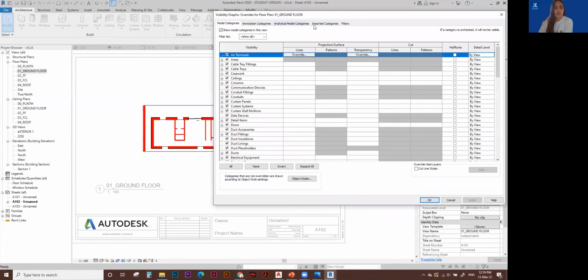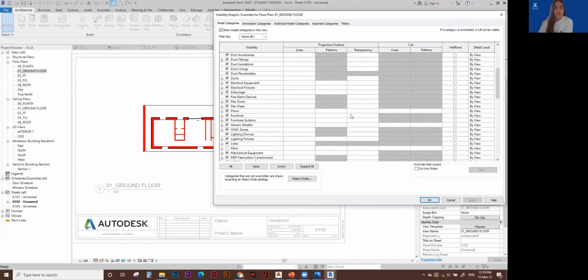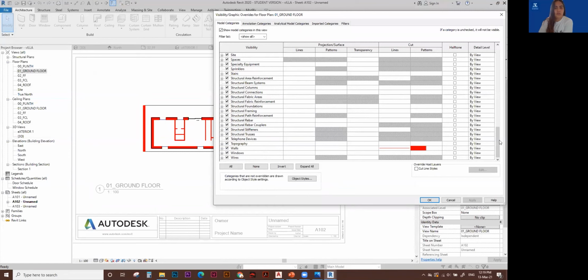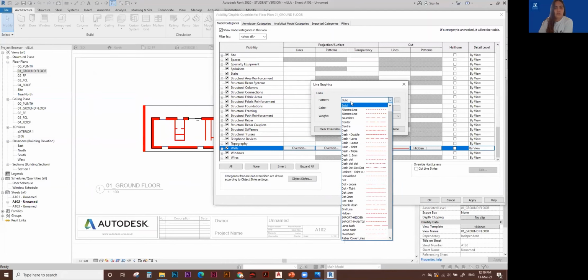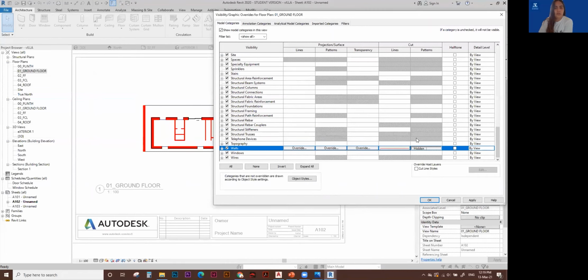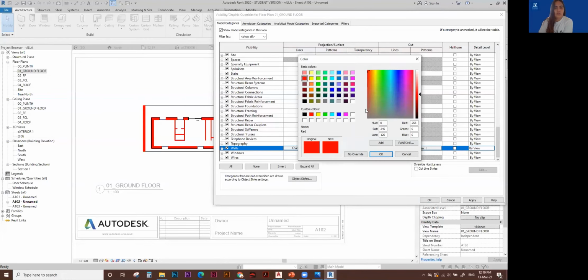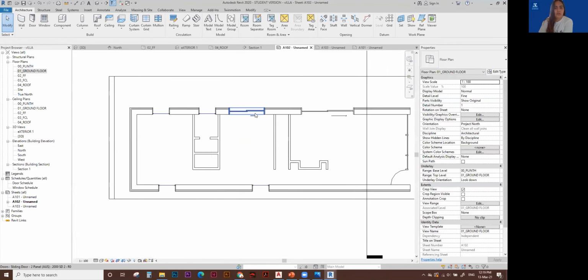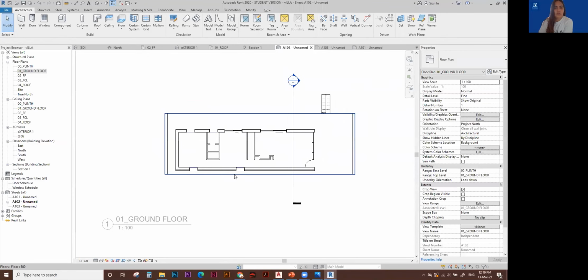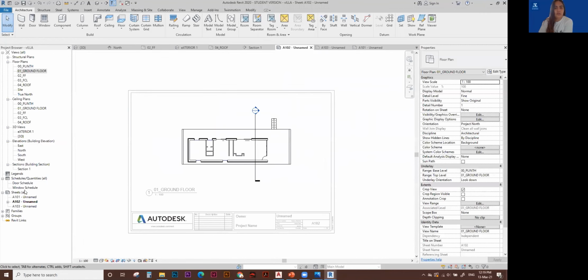It's going to override everything that we've created so far, with one specific value that you're giving inside the VG visibility graphic command. So this is a very powerful tool to control everything and override everything, which is why it's called visibility graphic overrides. I'm going to quickly undo this. No override. No override. Okay. So that's VG that we saw.